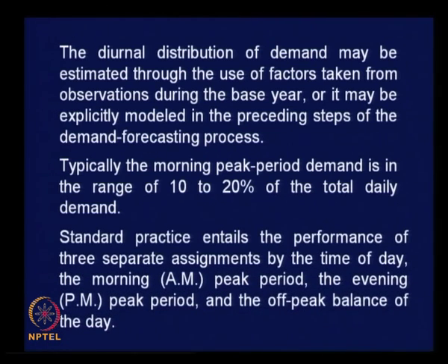Standard practice entails the performance of 3 separate assignments by the time of day: the morning AM peak, right, the evening PM peak, and the off peak balance of the day. You have to do assignment for 3 traffic demand situations.